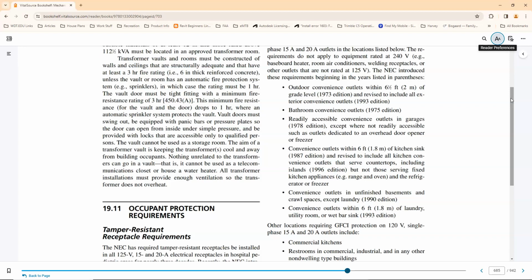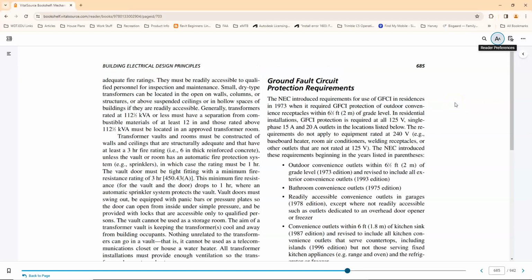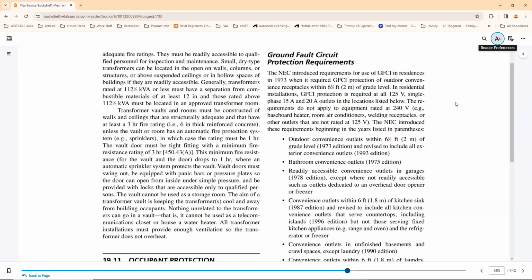This basement I'm working on right now, we're going to run all GFCI and AFCI breakers so that the entire circuit, everything connected to any circuit in that space, is going to be protected for both GFCI and AFCI protection. So if that trend continues, and I expect it probably will, it just kind of makes sense, we're basically going to start moving away from what is required to be protected with GFCI to what isn't, because it would be easier to list.